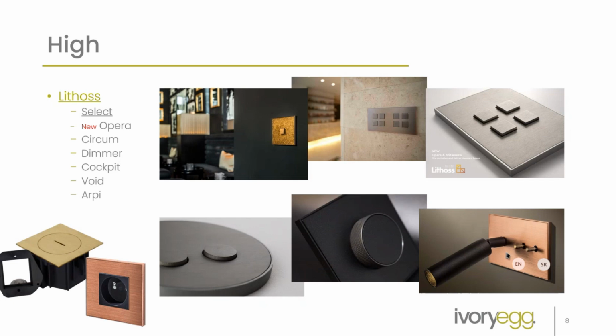Yeah, it's really important to know though, these cockpit ones are only 24 volt. So you will need an input behind them for whatever automation system you decide to use. Also, it's really important to note, apart from this range, the cockpit and the Esteem, which I'll show you in a second, all these other keypads can be 24 volt with LED. So what that means is you can also tie them into other automation systems such as C-Bus and Dynalite and have the LED working. As well, they work with Casambi. So like the rotary dimmer, I'm getting a lot of interest in that as well.